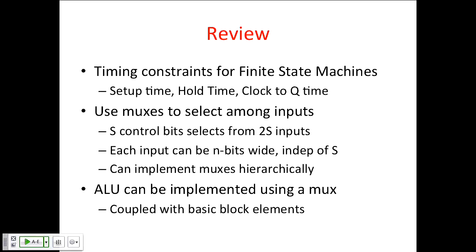So just to remind you what we looked at last time, remember, all the systems we're building are synchronous digital systems. They're synchronous because there's a clock that tells everybody when to move to the next cycle and take a snapshot of their inputs on the registers, and produce it on the outputs. And around those clock edges, there are constraints that all the physical circuits, these registers, have to observe. The signals have to arrive at least a setup time before the clock edge to allow the input to settle. You have to hold the signal stable for a little while after the clock edge. This is to ensure that you can reliably capture the signal at each register when the clock edge arrives. And then there's this notion of clock to Q time, which is not about correctness, it's about timing: from when the clock arrives, how long does it take for the new data to propagate to the output of the register, which is Q. That's why it's called clock to Q time.